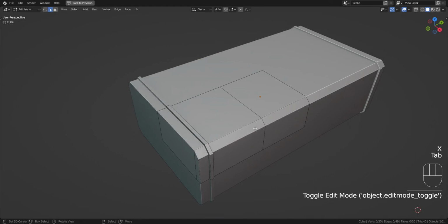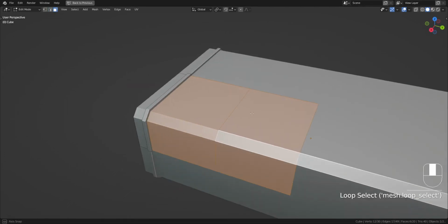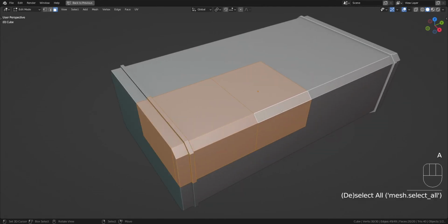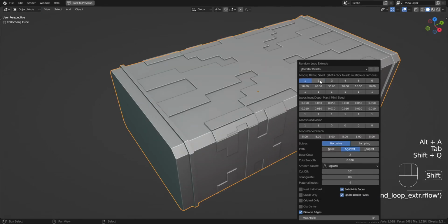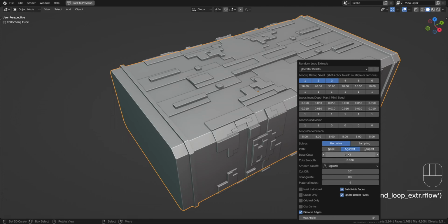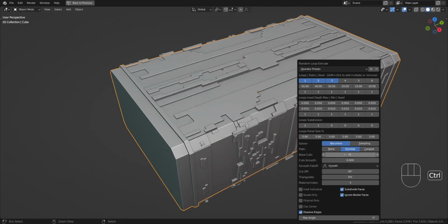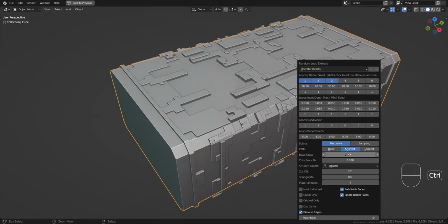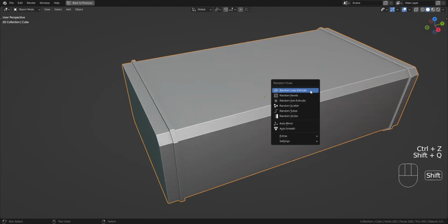If the base mesh has too many faces, then you can select faces by sets, and not select the entire face, or just select faces by region and apply the random operators to them, just to limit the amount of faces that you have to work on in order to avoid slowing down the operation when using the random operators.